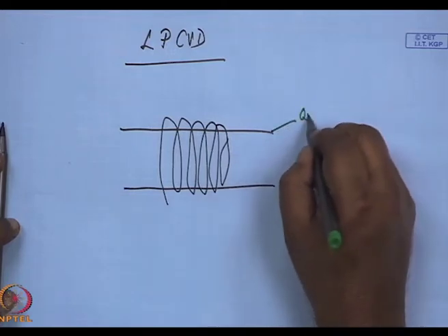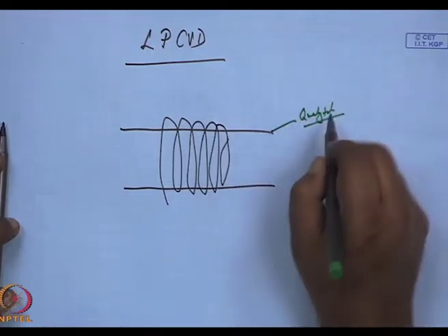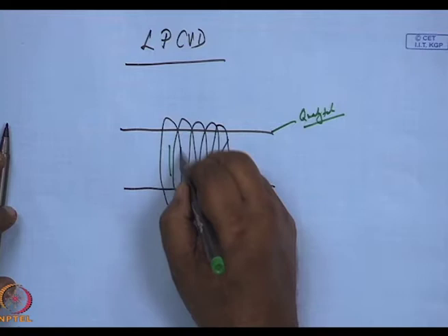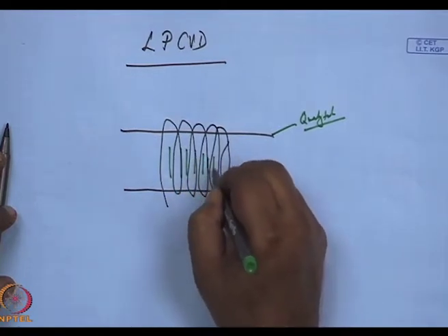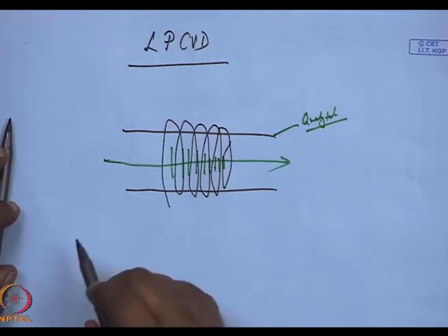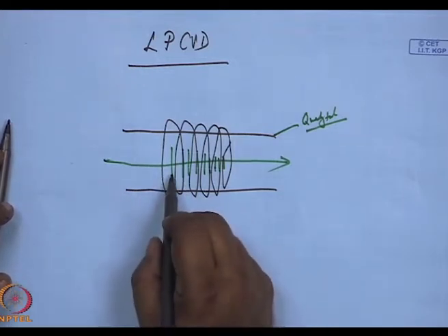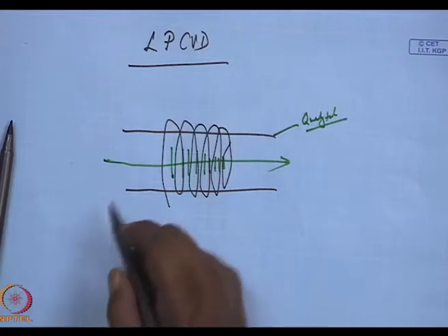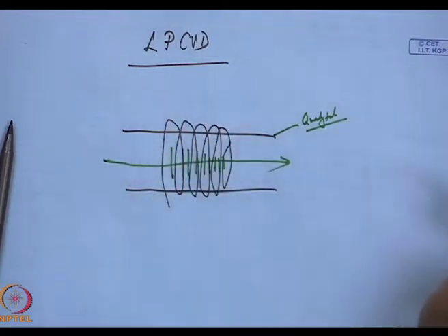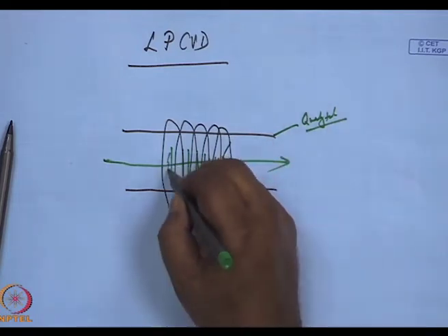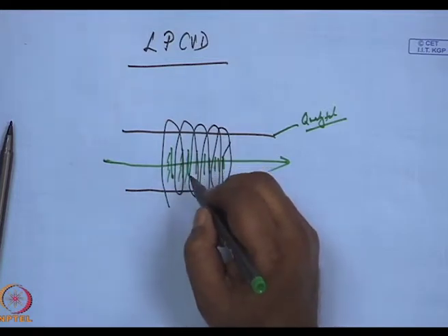This is a quartz tube. These are the wafers. And the process gas flows through in this way, thus coating the substrates by reaction of the process gas, which can be, as I said, tetraethyl orthosilicate plus ammonia, to give you silicon dioxide, which will fall on this surface.